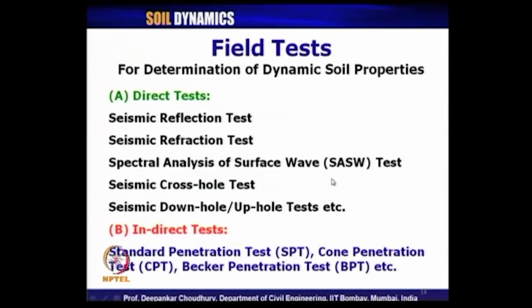What is MASW? The same spectral analysis of surface wave, in that case it is multi-channel. So, that is why MASW, but the methodology of the testing and principle everything remains the same. Only difference is instead of a single channel we use multi-channel. Then another direct test is called seismic cross hole test, and another one is called seismic downhole or uphole test. So, these are the different types of direct field test for determination of dynamic soil properties.